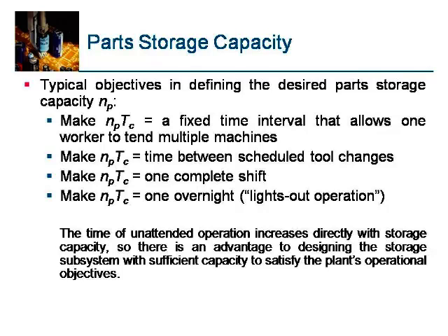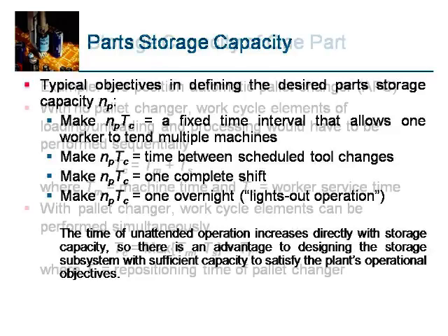make np times Tc equal to one complete shift; make np times Tc equal to one overnight or lights-out operation. The time of unattended operation increases directly with storage capacity. There is an advantage to designing the storage subsystem with sufficient capacity to satisfy the plant's operation objectives.